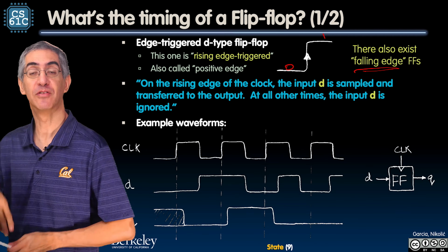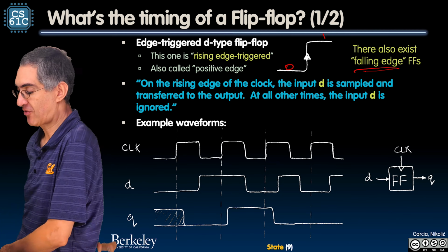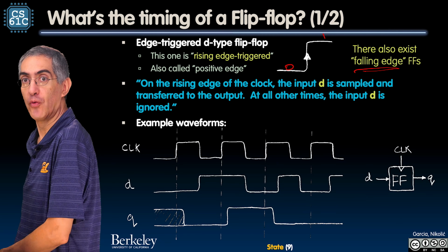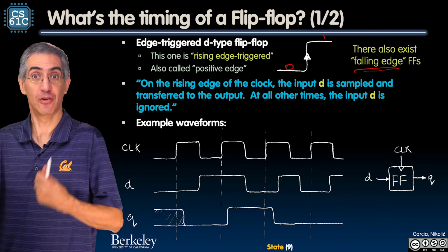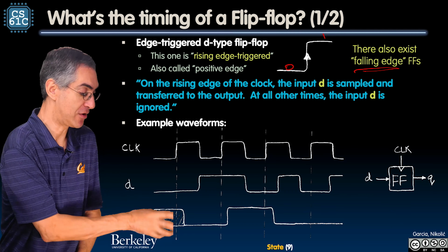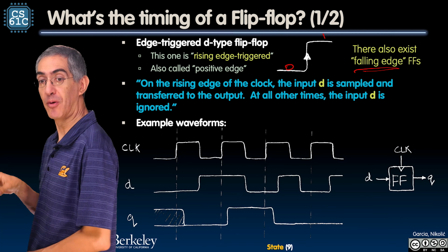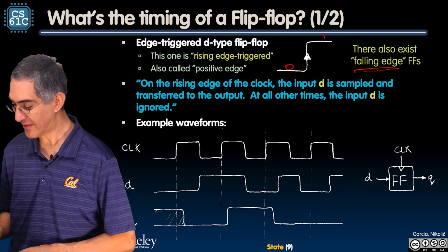At all other times the input is ignored. The input's changing, I don't care, I'm not looking at you. Only when I'm asked to load, when that rising edge happens, do I grab the value and have it on the output. That's the idea. So here's an example waveform.